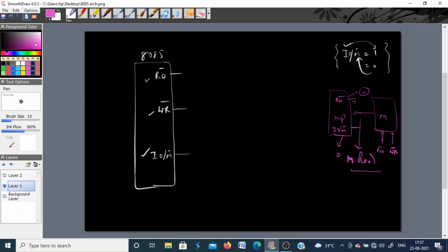Okay, so you cannot now see this read signal directly connected to this, because this read signal has to be connected to some input output device also. So how can you differentiate whether you are going to read the data from the memory or from the input device? For that we have one more pin here, IO/M bar. It has to be 0 or 1. If it is 0, it is a memory operation. If it is 1, it is an input output operation.